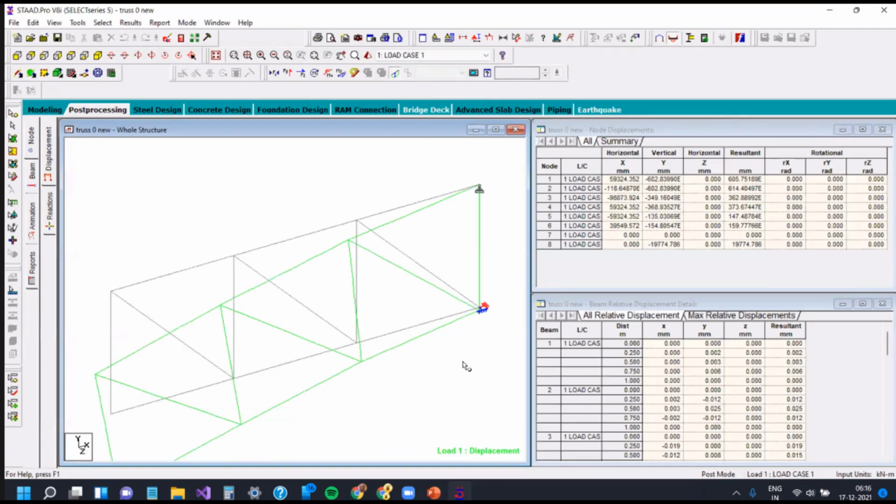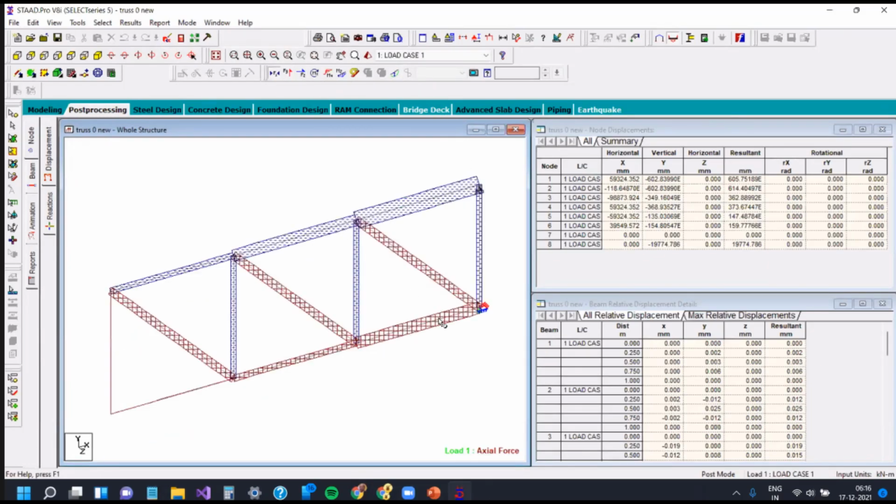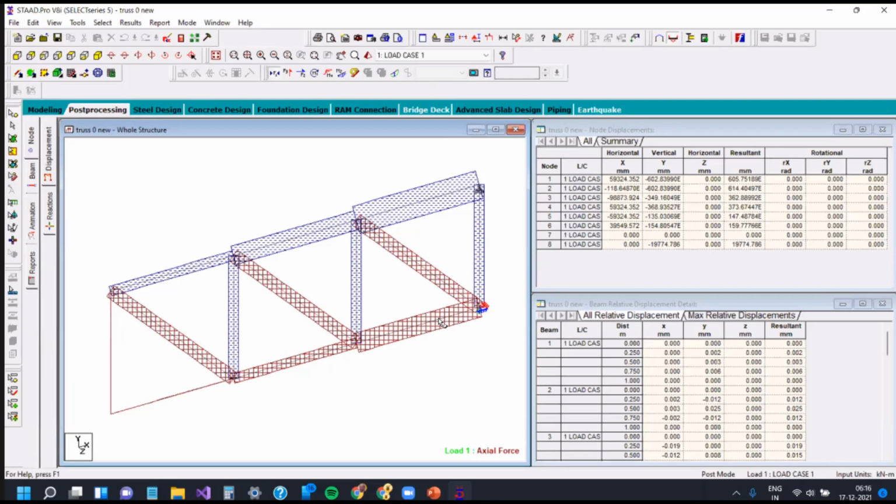Now imagine the load was at the tip of the truss. This is a cantilever truss, correct. Now, forget it. I go for the force transfer. What I want the young engineers and students to understand is how the chord forces vary. Because the bending moment diagram is 0 at the edge and it goes to the maximum at the supported end. Now you can see the chords. So from the edge to the support, the chord forces keep increasing because the bending moment keeps increasing.